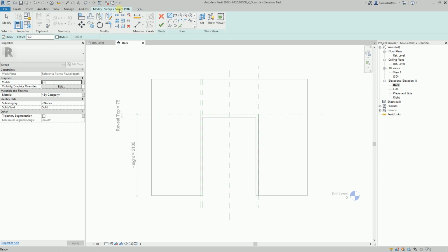So let's start building the path. I will use the Pick Lines command and put the Lock checkbox. I will indicate the left reference plane, then the top, and then the right ones. All our sketch lines immediately received locks that indicate their relationship to the reference planes.